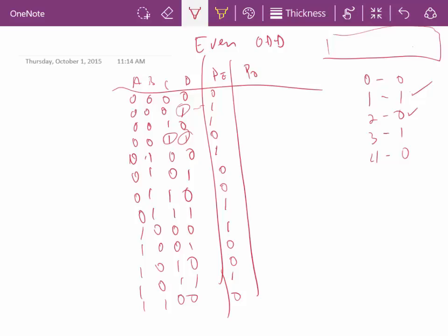And odd is just simply the reverse. We don't even have to calculate the odd, it's just going to be the reverse. So that's what parity is. The parity bit just goes along for the ride in order to help us. I'm going to transmit 8 bits over a serial cable. We haven't talked about serial parallel communications. At the end of the transmission, I want to know whether I've got the right data.